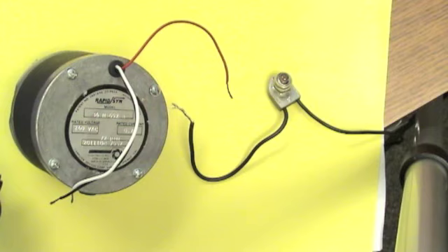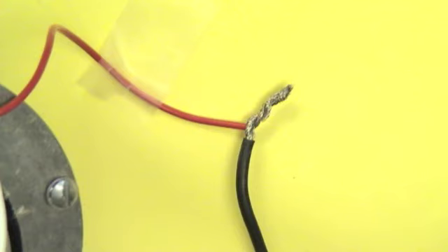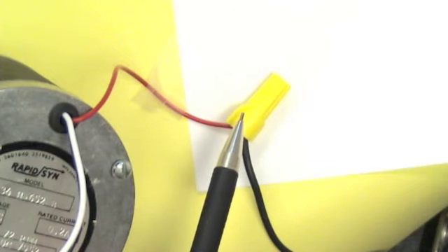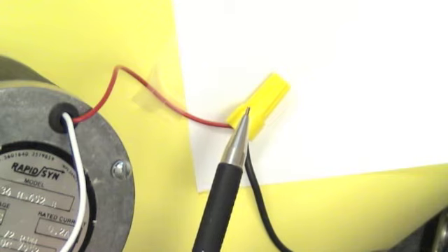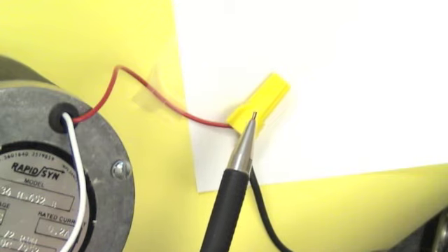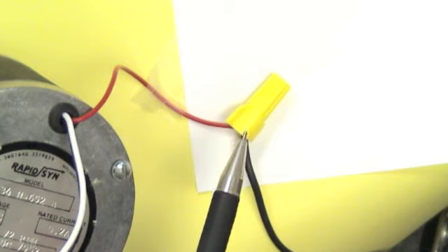Let's focus now on KCL, which is applied to nodes in a circuit. A node is an electrical juncture of two or more devices. Here we see two devices. This is an electrically controlled valve. Here's simply an on-off switch. Here the two wires have been just physically twisted together, and for good measure we can add a wire twist cap. And this would be an example of a node in a circuit, or it might be the juncture of two aluminum lines on an integrated circuit chip or two traces on a printed circuit board, but let's consider this as a concrete example for right now.